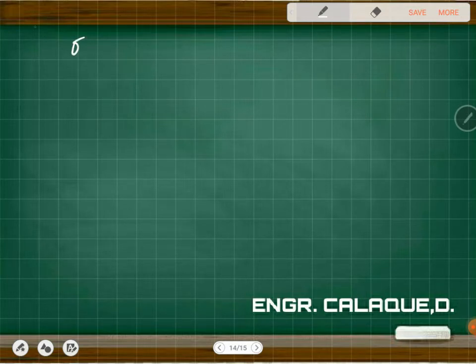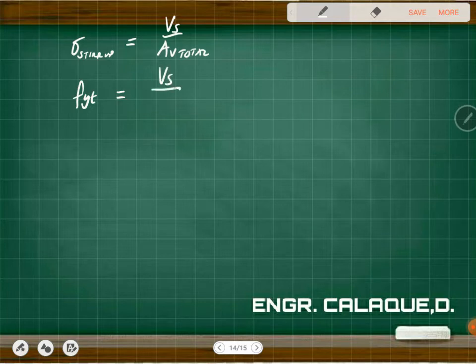So, yung stress for stirrup is just equal to the force of stirrup, which is yun yung shear, divided by yung area nung mag-shear total. Okay? So, yung stress ng stirrup is FYT. And then we have the VS. And then we have the number of A times V. Okay? And then yung N natin, that is VS. That is just yung effective depth divided by yung spacing ng stirrup. And then we have the EV.